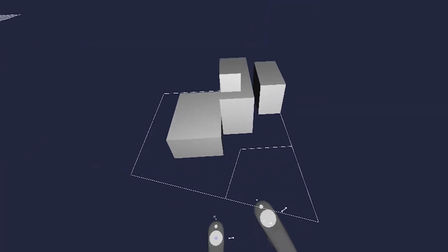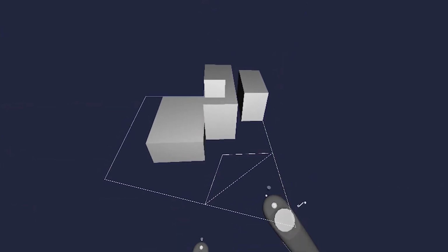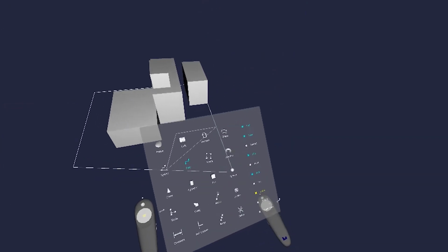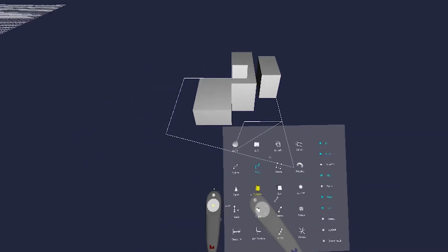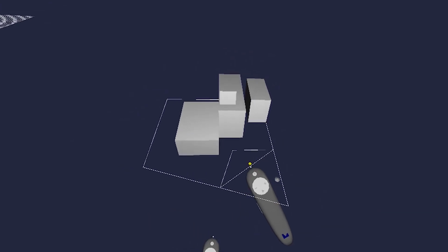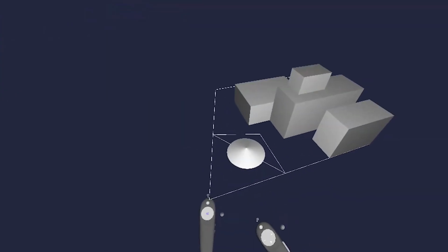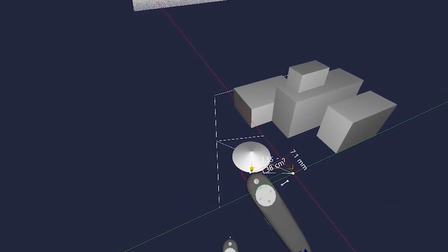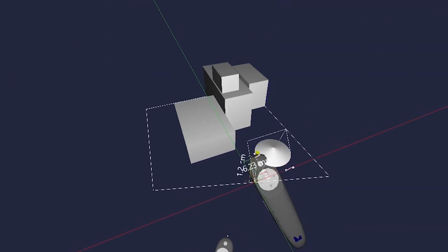Okay, so let's make a line between this point intersection and this point intersection. Next, I'll make a cone at the midpoint of this line, like a sculpture, so that I can illustrate the tangent snap, which is next. The tangent snap will allow you to click the outer edge of a circle from another point. In this particular example, I'm going to turn off my near snap so that I know I'm snapping to the tangent, like right there, and then on the other side, similarly from there to the outer edge.